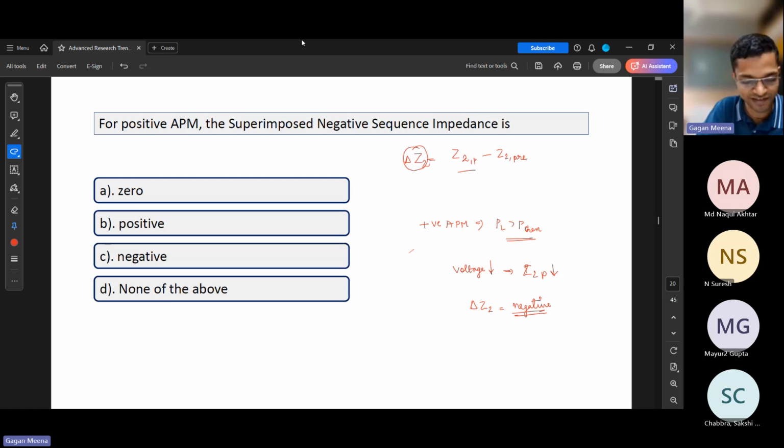When the load increases, to maintain the voltage, the current drawn at the remote end is increasing, so the voltage will drop at the remote end. We can add a capacitor bank, but for residential consumers we generally don't have capacitor banks. They are there for industrial and commercial consumers.